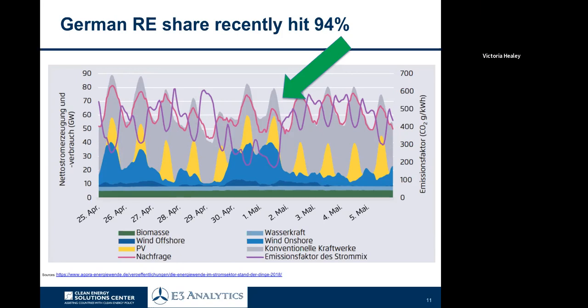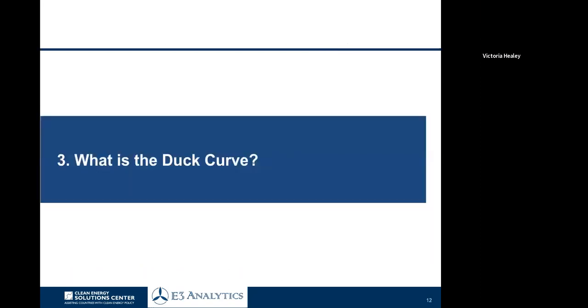It's important to underscore also that in Germany, renewables have priority in the grid. So, as we discussed earlier, when the wind blows and the sun shines, they have priority. And that electricity gets dispatched, gets taken first in the merit order, and other generation sources have to scale back. So this gives you a bit of an overview of the curve for a standard electricity demand profile in a market with a high share of variable renewables.